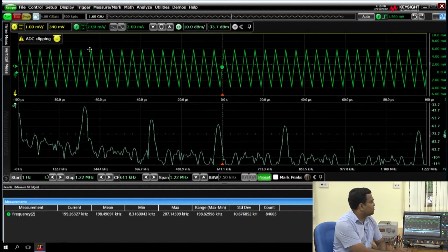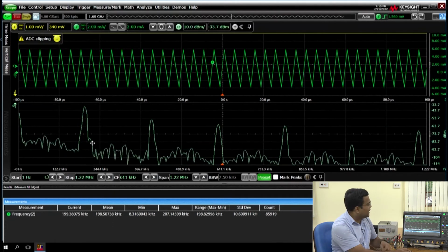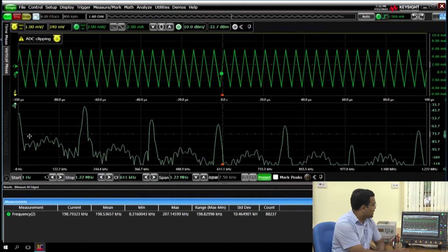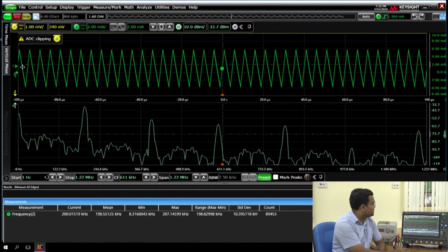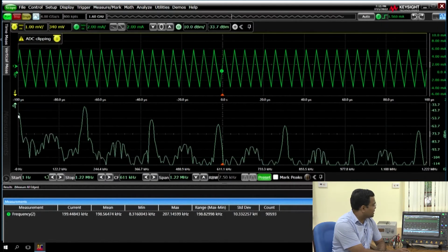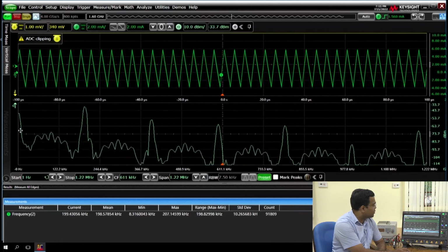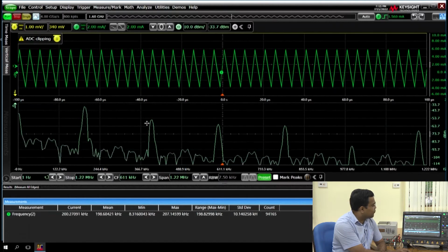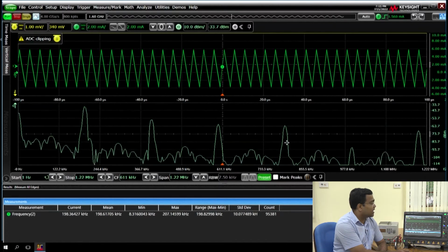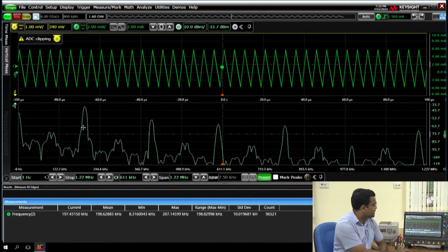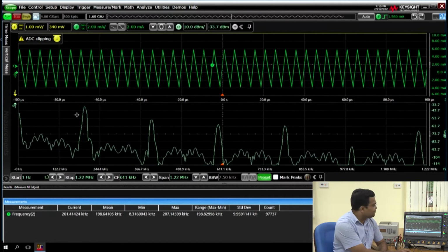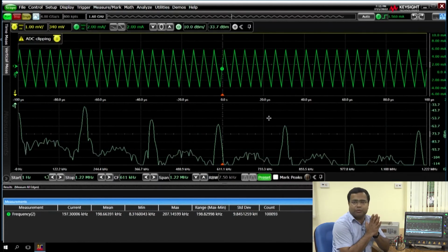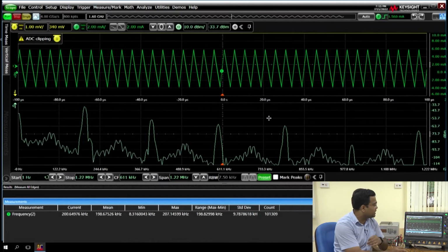It shows periodically stable behavior, and for the corresponding spectrum, if you take the power spectral density of the inductor current FFT, you will see, because it has some average value, a DC component at low frequency, and then this is the 200 kilohertz, and then 400 kilohertz and 600 kilohertz harmonics. So 200 kilohertz is the switching frequency, that means this is my fundamental component. This is under stable periodic behavior with fixed frequency pulse width modulation.